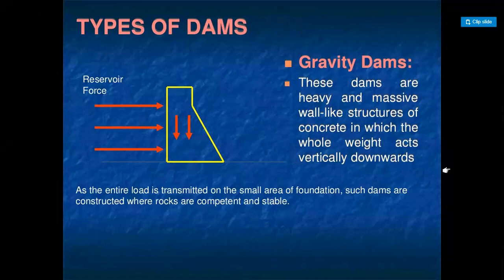Concrete dams are also known as masonry dams. Based on their geometry and the mechanics through which they transfer water load to their foundation, they are further classified into gravity dams, buttress dams, and arch dams. The earth dams are also divided into earth-filled dams, if the material used is predominantly earth, and rock-filled dams, if rock is more in the material used. The different kinds of dams are described in detail here.